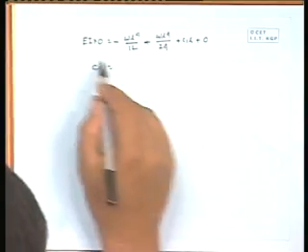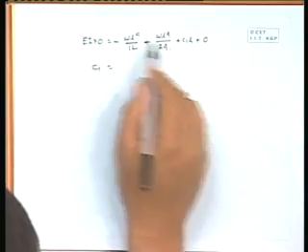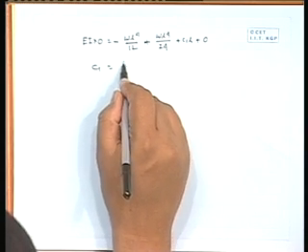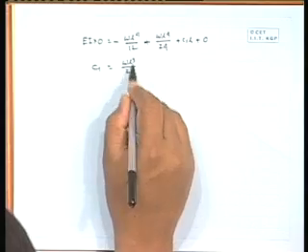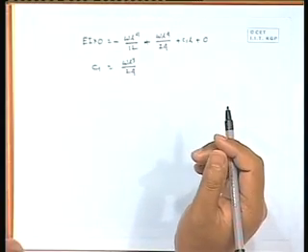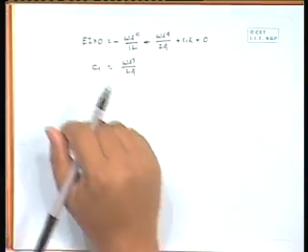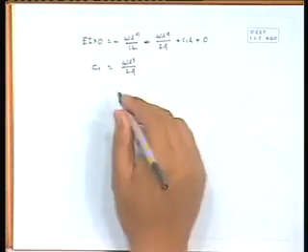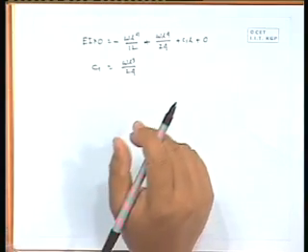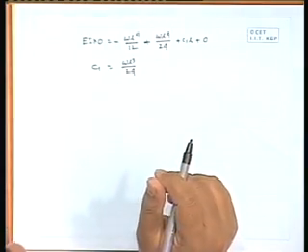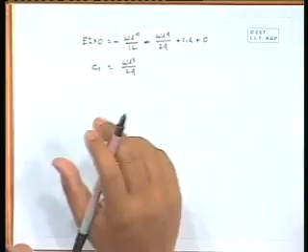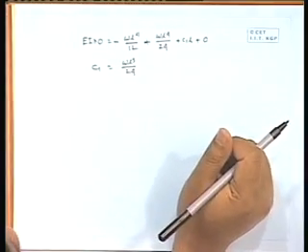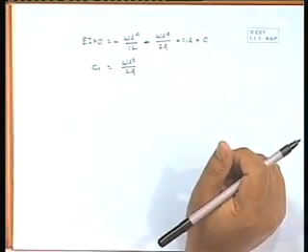So, C1 will be, this part is 0, this part is 0, the L will cancel, it will be omega L cube divided by 24, because it is 12, it is 24, half of that, and this is minus, it will go to the plus side. So, C1 is omega L cube by 24 and C2 is 0. Now, these two quantities we can put in the expression of our slope and deflection. We will get the equation for the deflection and slope of the deflected line.